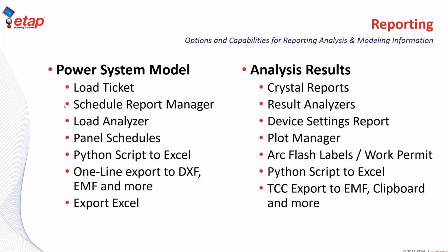The power system model reports include things such as load tickets or induction motor data specifications, a schedule report manager where you can generate MCC bus tabulation reports, transformer tabulation, cable tabulation, and so on, a load analyzer that allows you to generate a connected load report without actually running a load flow calculation, panel schedules which generate the connected as well as the operating load based on code demand factors. You can also use Python script to generate an Excel report, and you can also generate a report in Excel using the Excel open format. Graphical information can be exported using DXF, Metafile, and more.